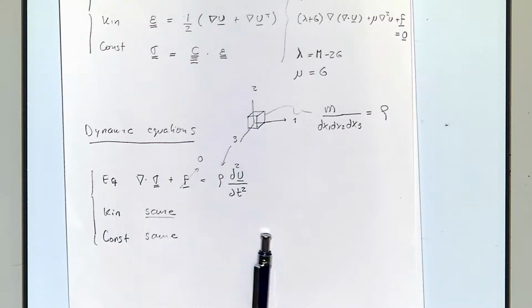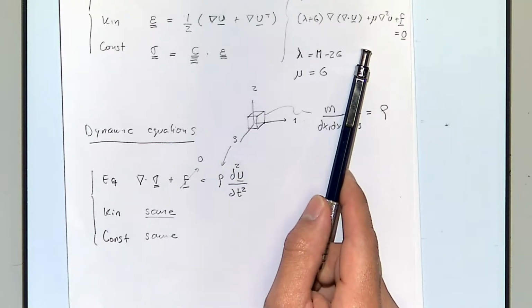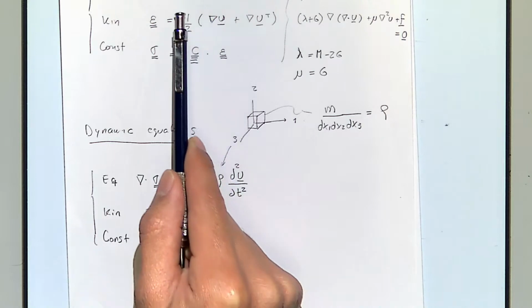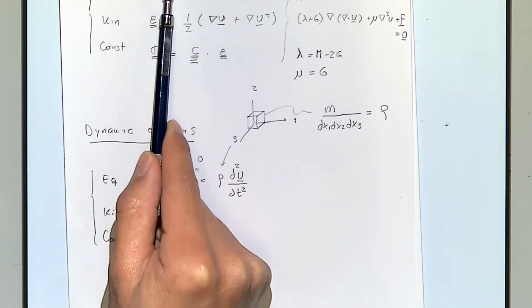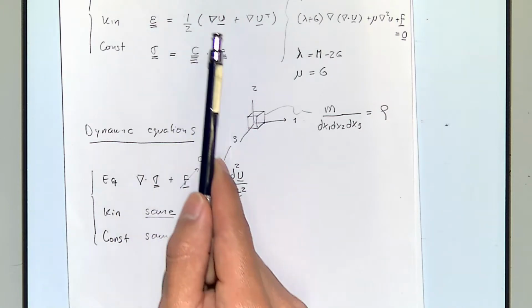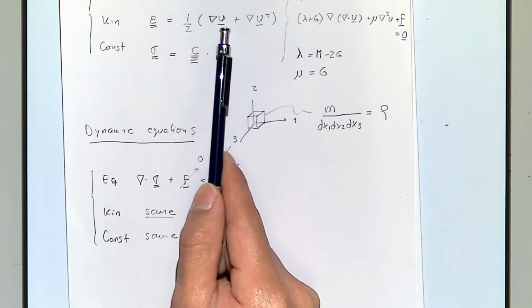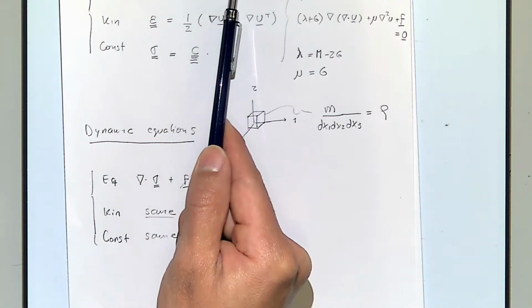So remember that in order to get here, what we had to do was to put this stress in there, and since now we have this equation in there, we had strains. In order to replace that into strains, we need to put displacements in there, but everything we have to do is just to add this term.